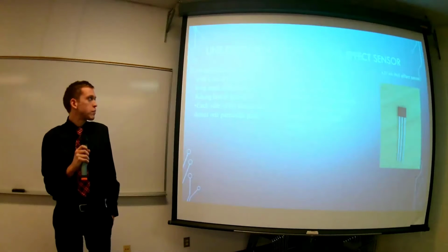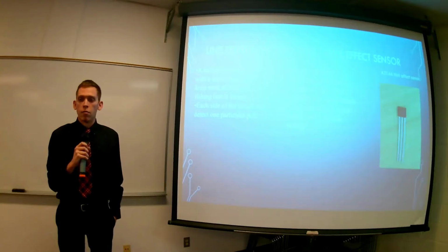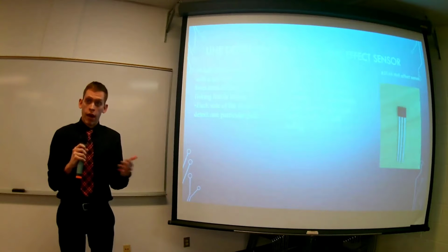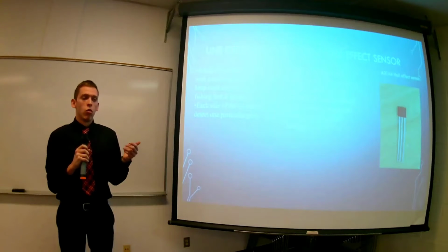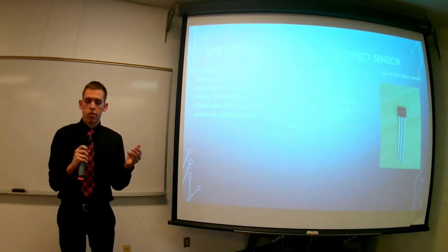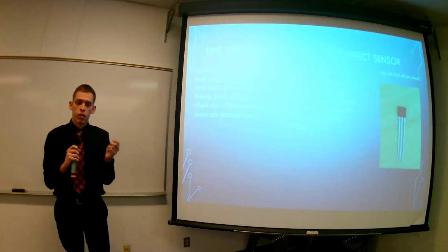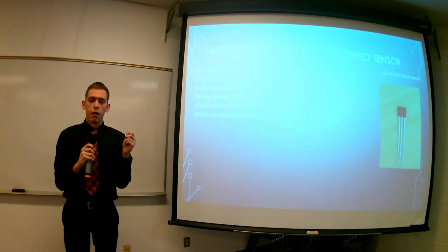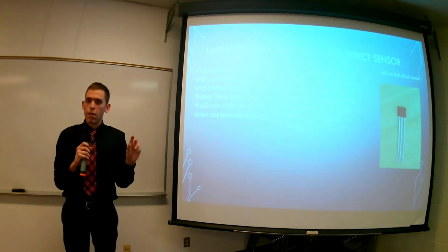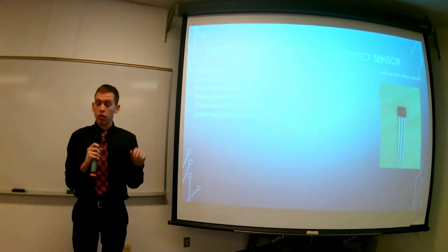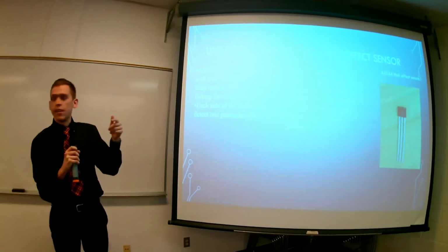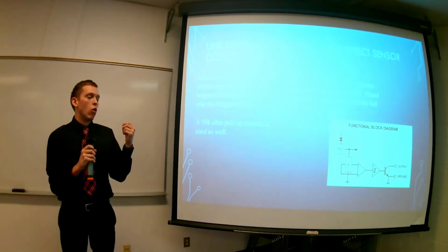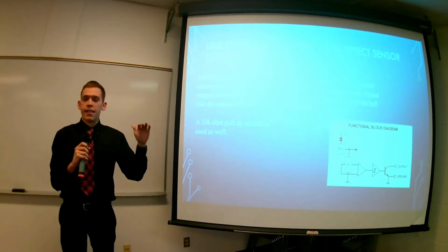Yep. So in terms of line depth, it's important to be able to track how much line you've let out, how much line you've let in, where you are at all times in the fishing process. So what we ended up using is Hall effect sensors paired with magnets. Each side of the sensor we chose can detect one pole of the magnet, and it's all based on the flux density, the magnetic strength of that magnet, to determine when the output goes high and low. So if you see on the next slide here, we went with the A3144 Hall effect sensor. As long as no magnetic field is detected, the output remains high.